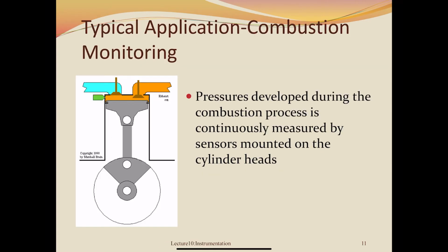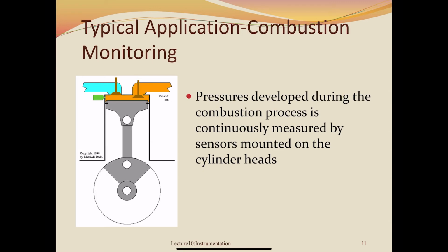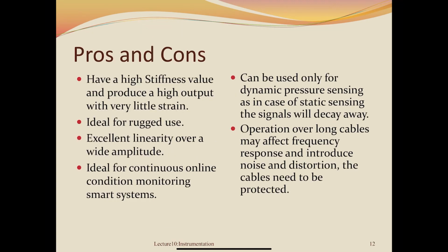A common application for piezoelectric sensor is in combustion monitoring, where it measures the pressure that develops during the combustion process by putting the piezoelectric sensor on top of the head. The advantage of piezoelectric sensor is that it will have a high stiffness value, meaning it will produce a high output with very little strain.